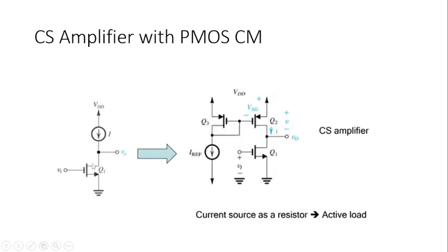So common source amplifier, this is the same circuit. We have taken NMOS Q1. Your current source is here. Now this circuit has been changed to the current mirror. So here Q1 is your NMOS transistor, and this is your PMOS transistor. Q2 is PMOS and Q3 is PMOS, and this part is your current mirror circuit.